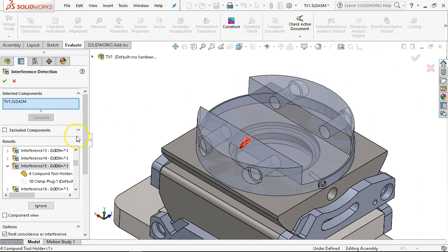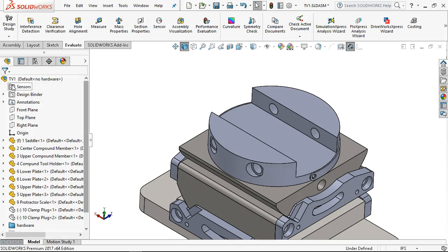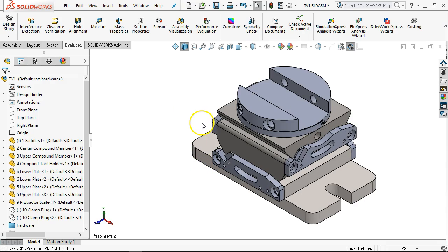What I would want to see is, regardless of the hardware, one of the reasons I told it to remove it, was none of that is really a great big surprise. What I'm looking for is a gross interference, that, whoops, I missed a mate, and this thing is 1/8 of an inch into this part. I missed a dimension, and there is enough of an overlap that there is a serious gross error. And so, if we can catch those.